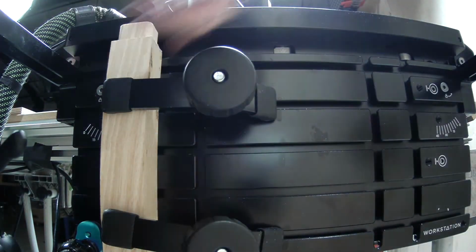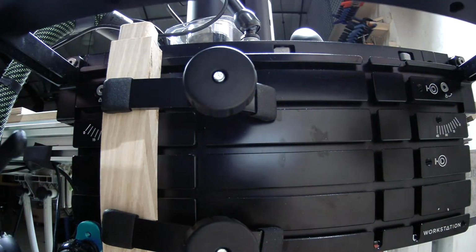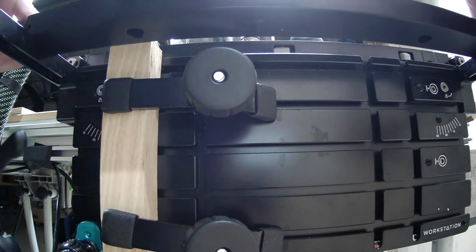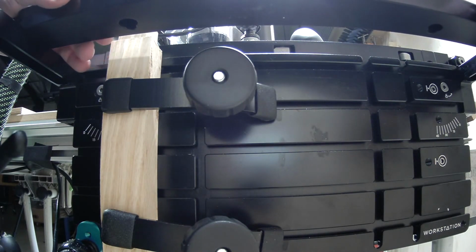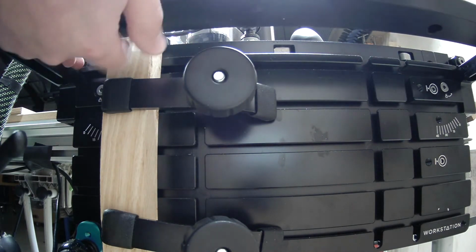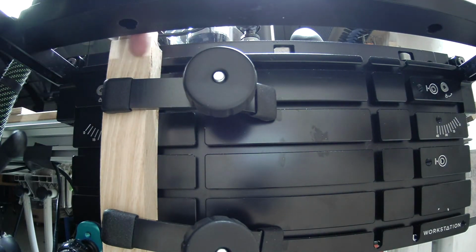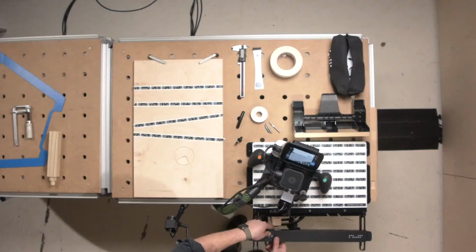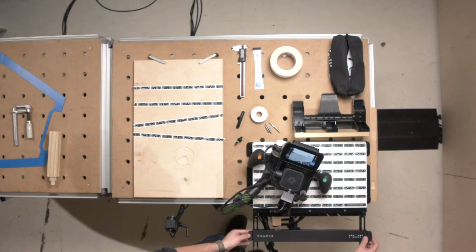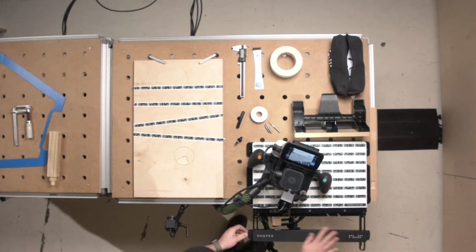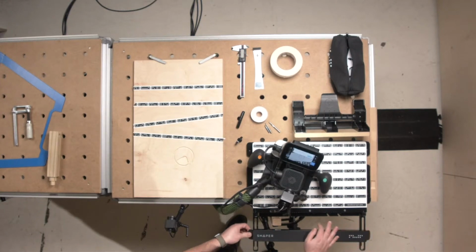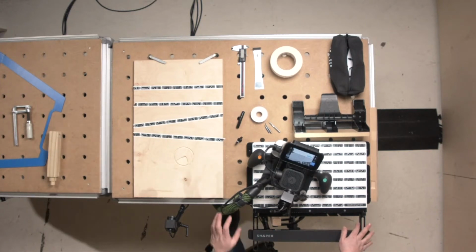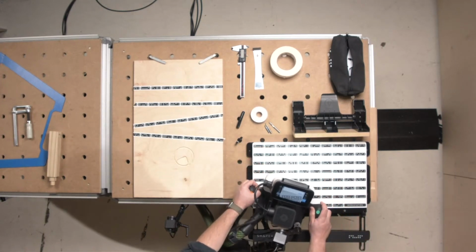Okay, and I'm going to take my support bar, and I'm going to set it up, like I said, with enough distance right in here where my finger is, enough distance that I can slip a finger in there, maybe double my finger, just something that you are comfortable with so that you know that your bit is not going to run into that. And with offsets especially, you can kind of forget what's going on and easily run your bit into things. So I like to give myself some extra wiggle room there.